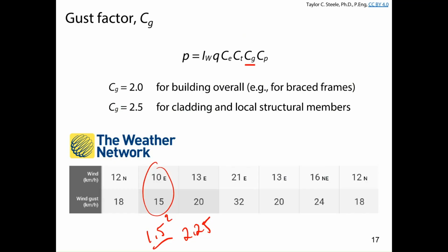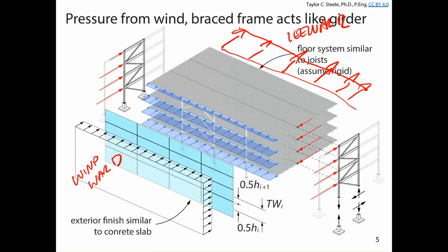The wind, we assume, is more or less uniform, but really as the wind blows, the pressure might be higher up here at a certain instance than it is over here. And then in another instance, it might be higher down here than it is to the right. So from time to time, the wind at a specific location of the structure is going to be more significant than elsewhere. And so locally, there's going to be a larger effect.